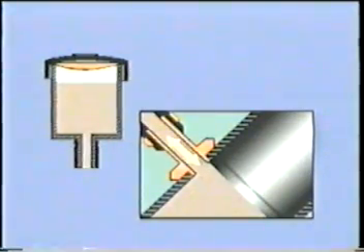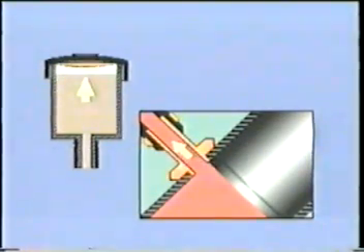This opening also serves to equalize the pressure in the system. When the orifice is open, the hydraulic fluid can freely expand and contract by flowing through the orifice and into the reservoir and deforming the soft diaphragm inside the reservoir cap. When the system heats up, the total fluid volume increases, but the excess volume of fluid exits through the recuperation orifice. The amount of compressible fluid in the hydraulic lines remains the same, so that the slave cylinder stroke is always the proper length for correct actuation of the clutch.